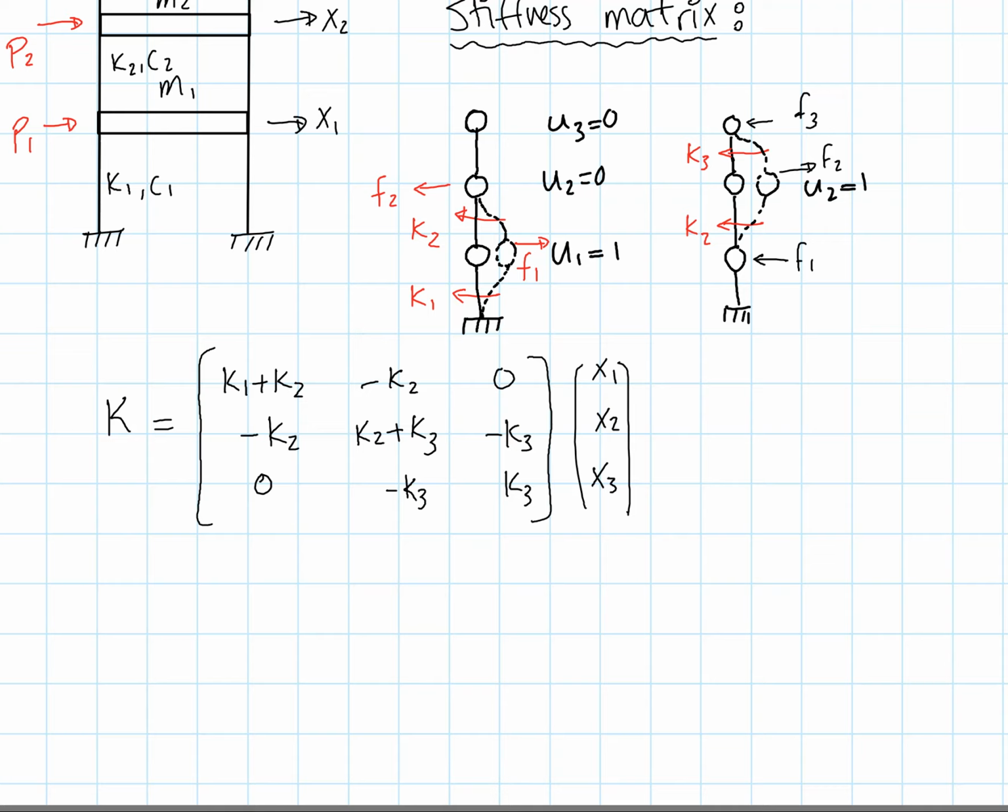Alright, so I could do the same thing for damping. Stiffness and damping have the same relative concept. They are activated in relative terms. So these x's that I've drawn, these degrees of freedom that I have, are my relative degrees of freedom. And so when I'm expressing this column vector in terms of my relative degrees of freedom, I can treat stiffness and damping the same way.